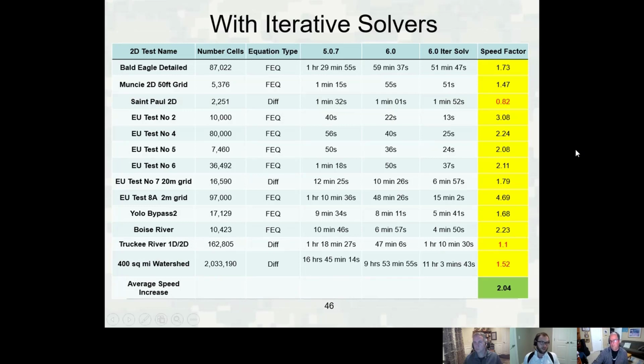So if you have a larger model, and maybe a model that you're going to have to run for a number of different scenarios, multiple times, maybe it's a dam breach model where you're running a bunch of different dam breach analyses, it's probably worthwhile, once you have the model stabilized and where you want it from a stability standpoint, to test it with these 2 different solutions and see which one's faster, so then moving forward you know which one to use, because that's a significant difference.